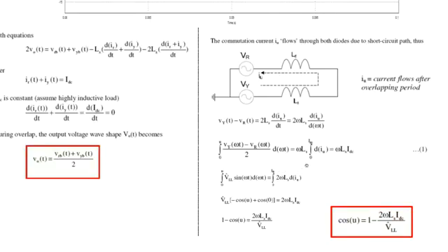Okay, I think we have solved this before. So you cross multiply the right hand side and you solve that, then that gives you the equation of V peak line to line minus cos u. Solve that, and finally you find that the equation to describe the overlap angle is cos u, or you can take u equals inverse cos of 1 minus 2 omega s Idc over V peak line to line.